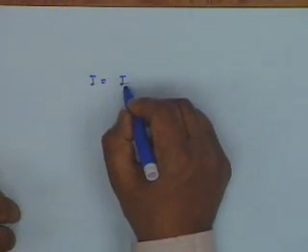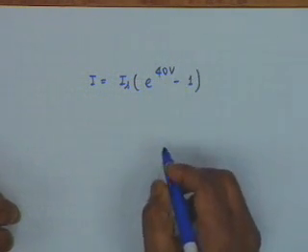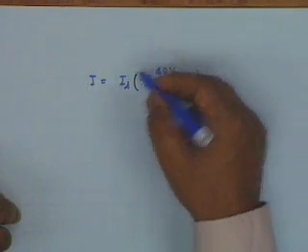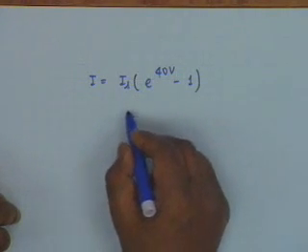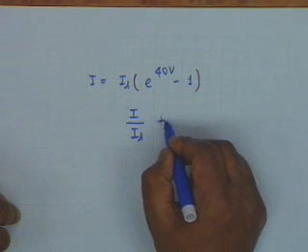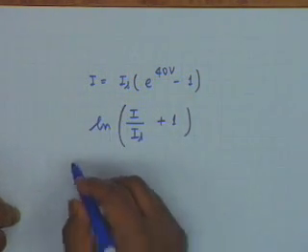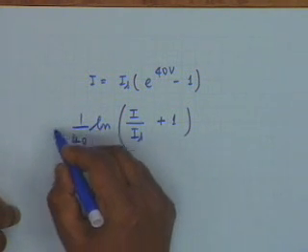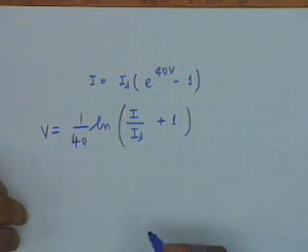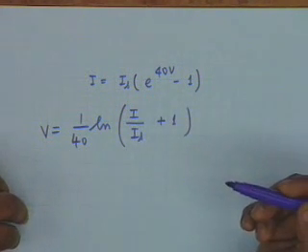The last part of the question asks, what is the voltage if capital I is 18 milliampere? We go back to the equation, that is capital I equal to Is times (e to the power 40 V minus 1). We have to find out V if I is given, and the simplifying feature is you divide by Is, add unity, take ln and divide by 40. This will be V, and in most cases I by Is would be very large compared to unity.